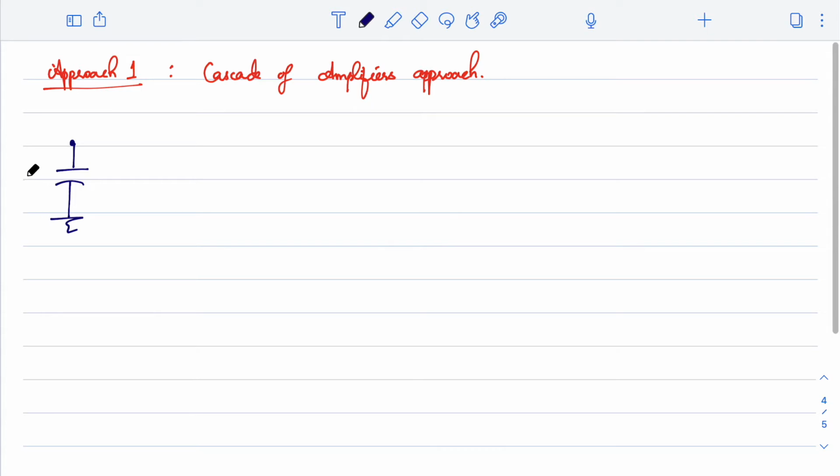So if you have some voltage here on a capacitor, delta V, because when you talk about a comparator, you can also think about the previous stages we discussed. You will have a signal, you will sample it, you have a sample and hold circuit, and you are getting the signal. Then we spoke about amplifying those signals with the help of switch capacitor integrators and other things. Now if you have a signal on a capacitor, how you can compare and make a decision whether that signal is greater than or lesser than a reference voltage is what we are going to do now.